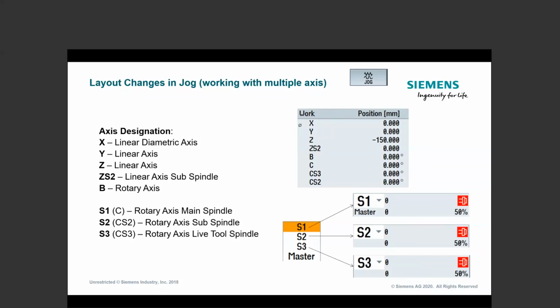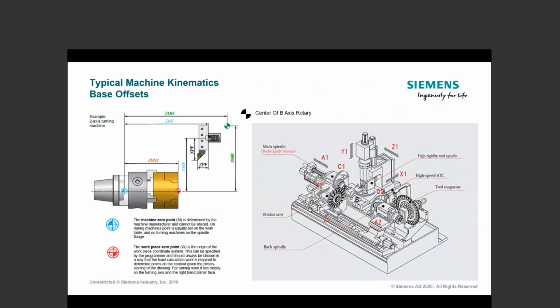So if you take a look at the total axis count, we're at what, 3, 5, 8 axes. And I mean, that's not uncommon at all when you get to this type of technology. So how would it look? How does it get commissioned? It's important to understand where the datums come from when we get to this type of technology and we start to have multiple spindles and we can do handoffs.